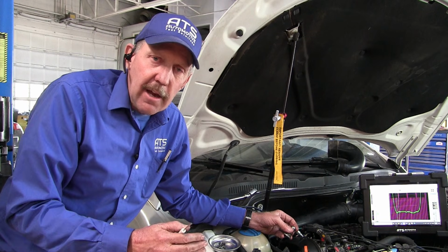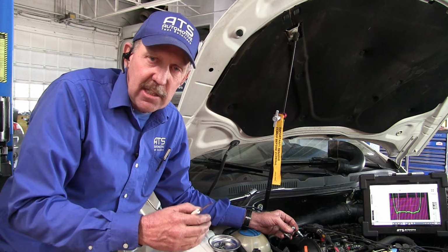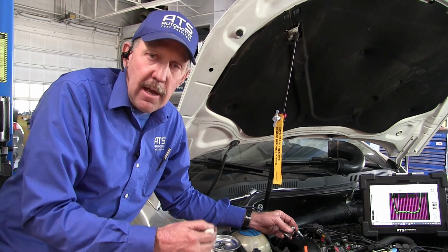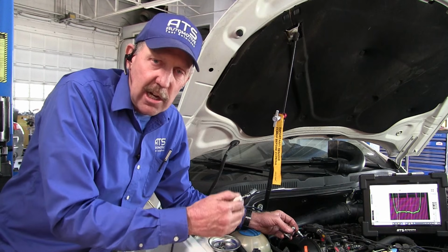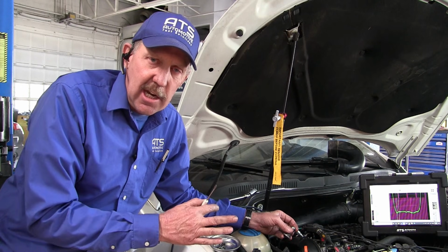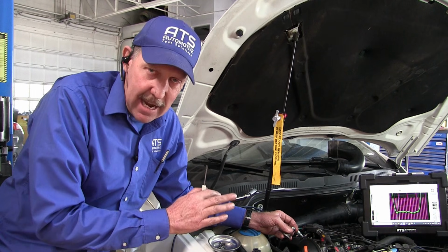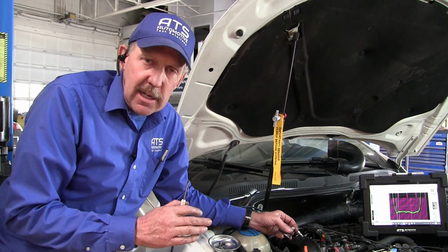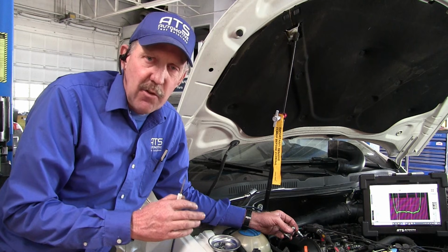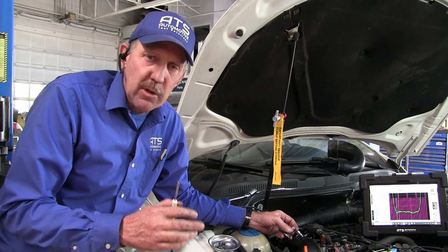The crankshaft sets ignition timing in the program. The camshaft sets the induction system up so it knows what stroke it's on. Now the computer will know when to inject the fuel. But when it's not sure where the injection point is on a GDI, it'll just shut the injector off. Again, that shows me that I have a cam problem. Then we looked at it and we could see that the compression waveform, the in-cylinder waveform, is out of time, and we also could see that the induction waveform was out of time.